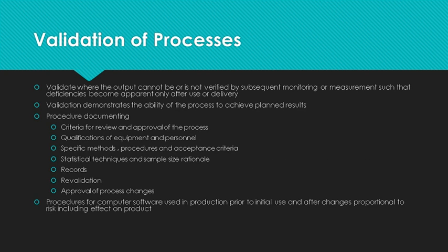Now this leads us into validation of processes. A process where you can't measure conformance and deficiencies will only be apparent when the customer uses the device must be validated. This confuses many people. If you can measure the device and it is still within product characteristic requirements, for example, your testing is non-destructive, validation of the process is not required. If you can only determine conformity with destructive testing, then validation of the process must be performed.